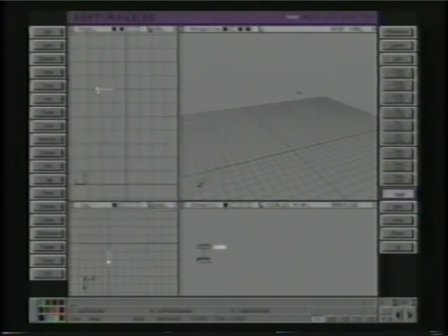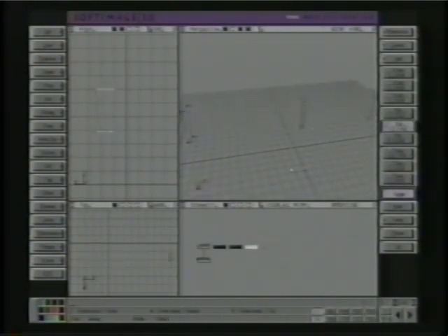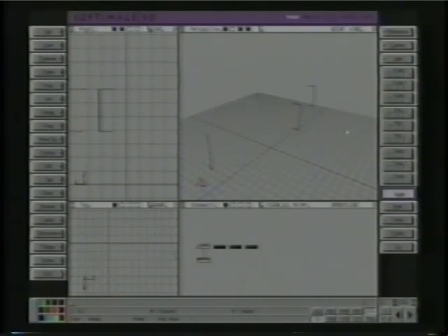Linear curves can come in handy. One thing you can do is skin the linear curves using a different format the other direction. For instance, let's say you wanted to make a belt. We could make a shape like that, and then just go ahead and duplicate that with the D hotkey, and then move that over there. Duplicate it again, move it over there. Now maybe I want to rotate those a little bit, and then maybe move this out like that. So here I have my 3 linear curves, and I can skin them using a different format the other direction.